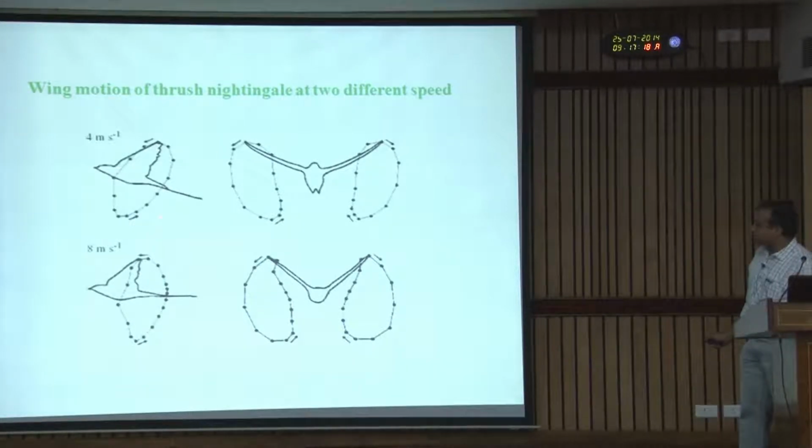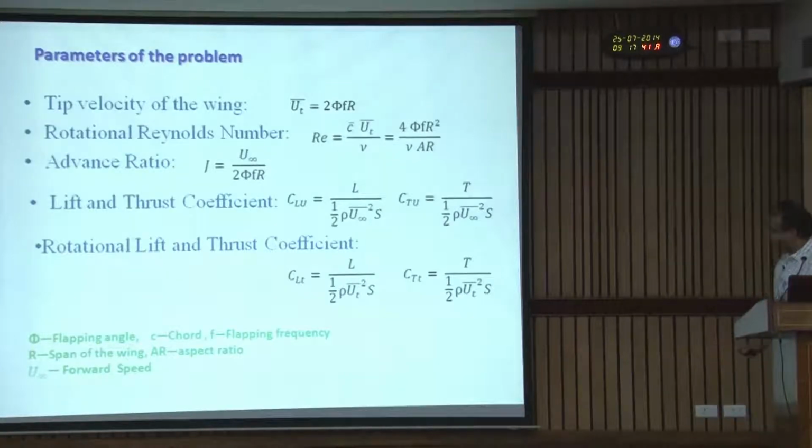At 4 meter per second it is the low speed. So, to generate sufficient lift, it creates an incident angle which is more, so that it can get a higher angle of attack in each section also. So the complexity is manifold in this, not only flexibility, but also the kinematics. So exactly designing any such thing is very, very difficult.